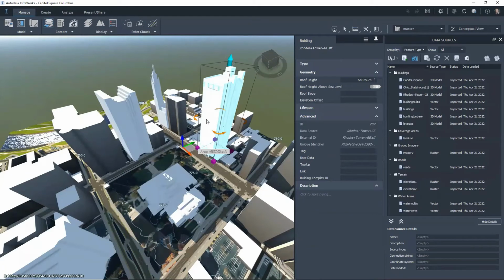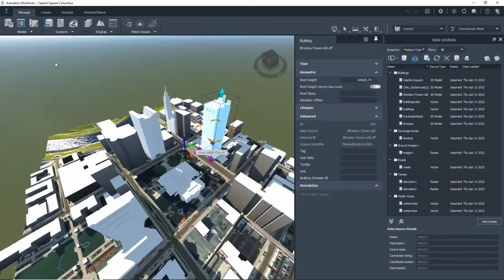If that is the case, you can go into SketchUp and flip the faces, and in some cases you want to keep the material there but flip the face. If you've used SketchUp in the past, you know the white and blue faces. If it's a negative face that's sticking out, or a blue face that's sticking out, it won't show up and won't render here. So that's something to keep in mind.